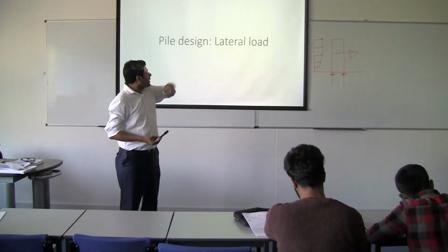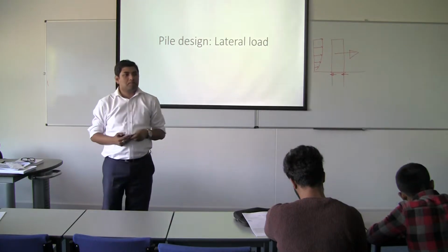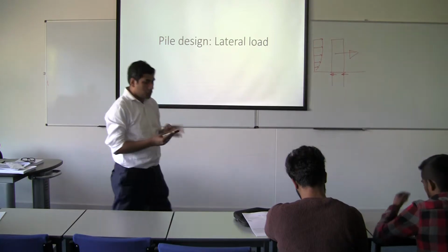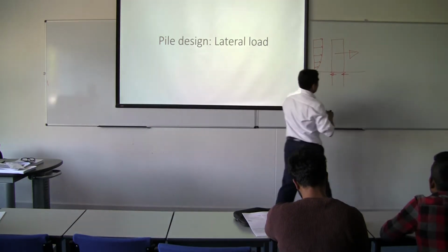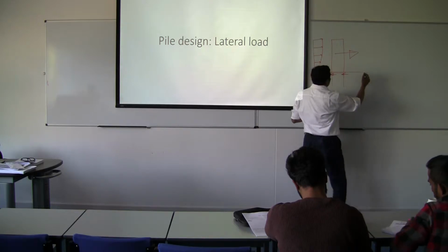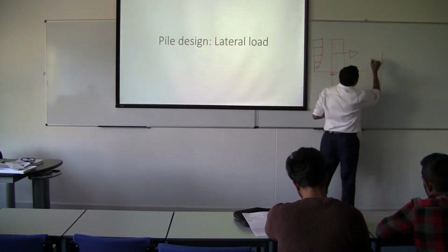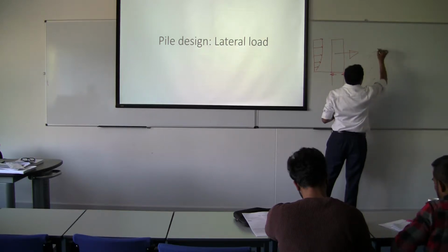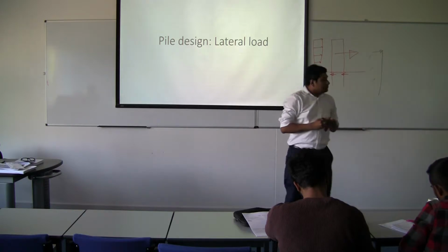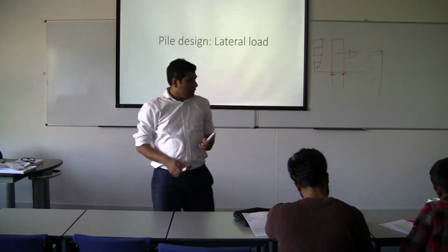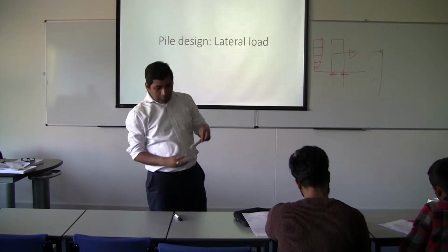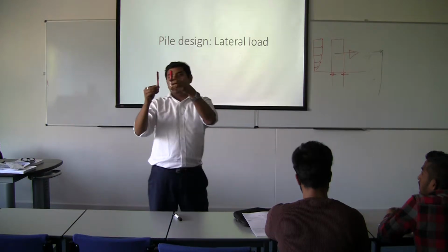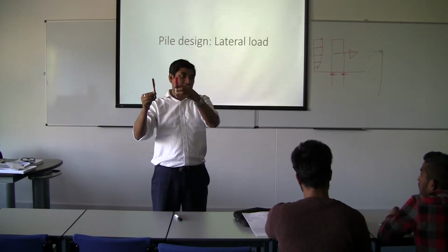Okay, so how do you take into account in the design? What are the things you must consider? Shear, bending. Yeah. So basically, let's now have the problem that you have got a pile here, right? And that's the soil, and you have a lateral load there. So think of this. You have in one case a pile which is short and stubby. In another case, you have a pile which is long and slender. Will they behave similarly or behave differently?